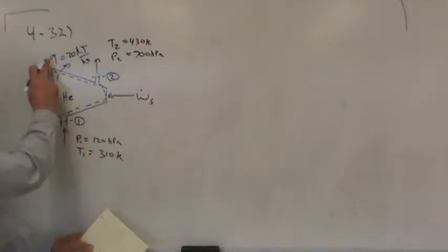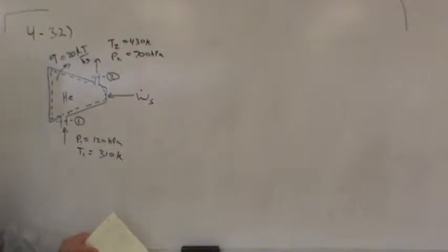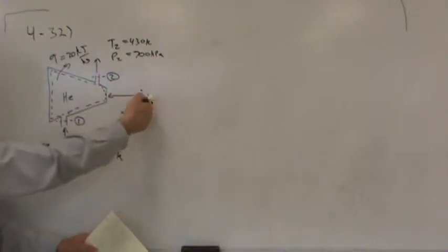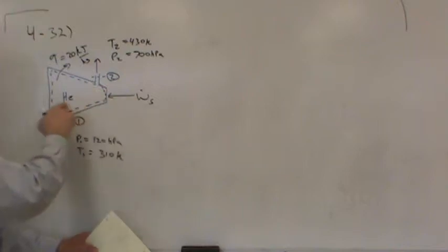Where do you think that heat comes from? Well, if the helium leaves with more energy than it came in with, then this heat loss must come from the shaft work. So the shaft work is not only compressing the helium, but providing for the heat loss.